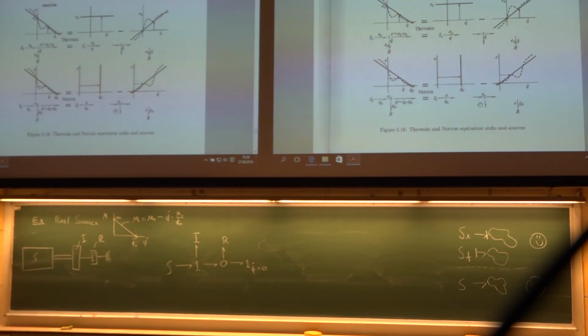And now simplify. 0 rotation. Okay, you have some torque attacking the wall, but it's not rotating. 0 power. We remove this bond with no power. Then this 0 junction can be removed, it has only 2 bonds. So away with it. And then we are left with S hitting a 1 junction where we have an I and an R. That's it. That's all we have.